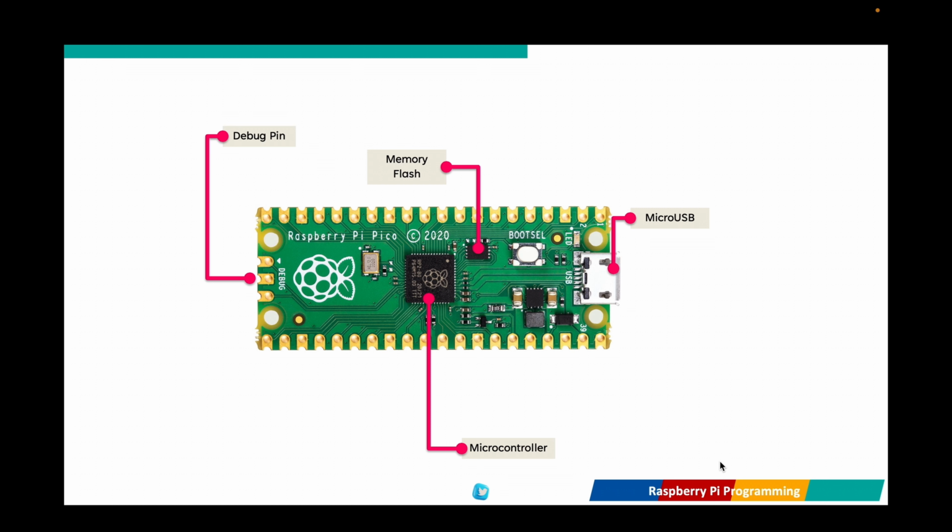A unique feature of Pico is its programmable I/O (PIO) blocks, which allow custom protocols and high-speed data transfer without using the main processor. This is especially useful for handling LED matrices, signal processing, or even VGA output.